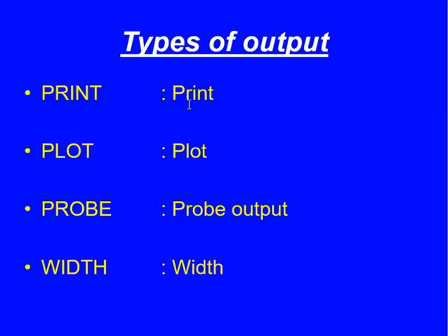If we want to plot our output or any other electrical parameter, we can use the .plot command, which will plot the waveforms. And the .probe command is also an output command.